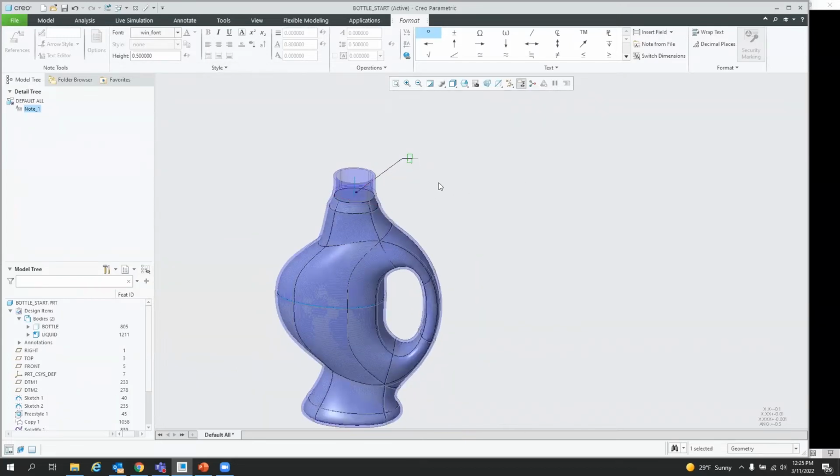And we're going to type in that cryptic name that you have to always look up if you don't do this a lot, which is ampersand gallons, colon, feature ID underscore. And since I have my feature IDs conveniently turned on over here, I can see that analysis is 1237. So I can just type that in. And maybe I put a space and gallons after it.